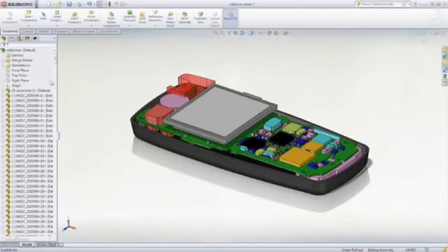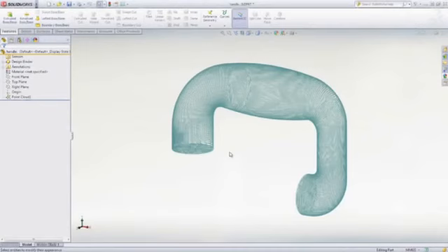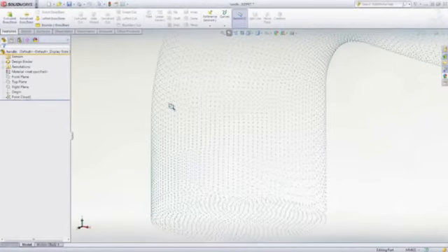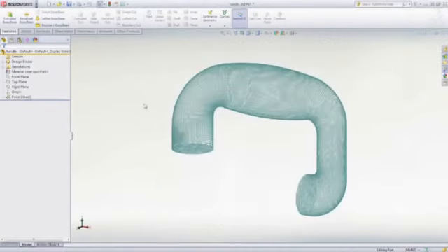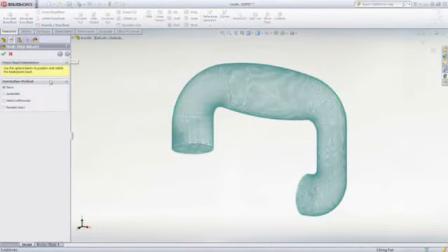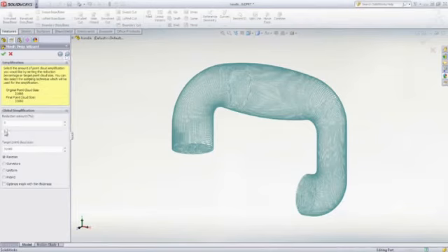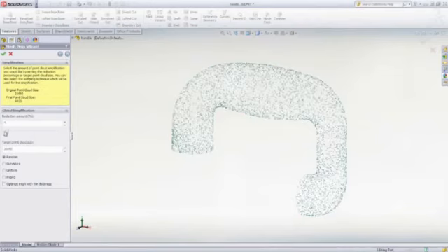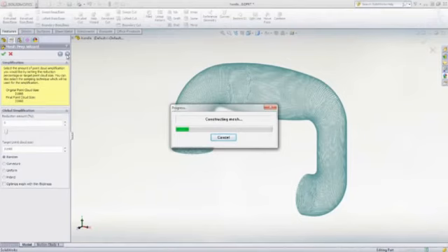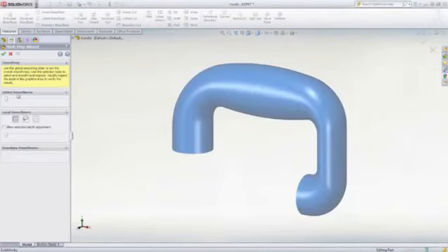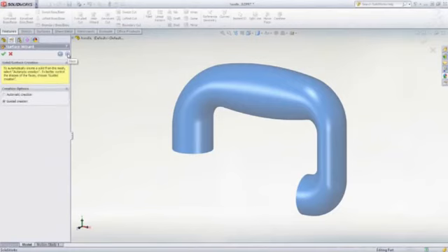When ready, the board can be built as a 3D assembly model from the customizable component library and readied for use in your designs. The Scan to 3D feature allows you to import scan data, mesh and point cloud files into SolidWorks and then convert it to a 3D surface or solid model. It uses a guided wizard to position the point cloud and remove noise or extraneous data such as fixtures that were used during the scan process. The simplification feature can be used to reduce the number of vertices to yield a more efficient mesh. And finally, the model can be smoothed to help rectify jagged or unrefined areas.